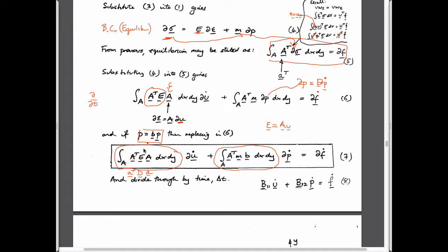If we want to backtrack a little bit, we realize that this equation on the left-hand side is our second order of displacement with respect to x, which is the equilibrium equation with the strain displacement equations in it, kind of the Navier equation as a function of d2u/dx squared. And this actually looks a little bit familiar to us as well. If you remember, we have also seen a matrix that looks like, let me do it in the terminology we've used.